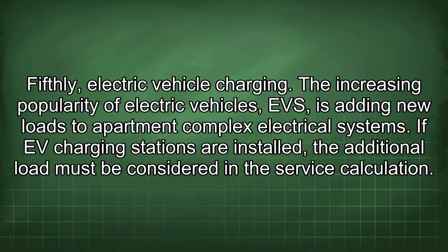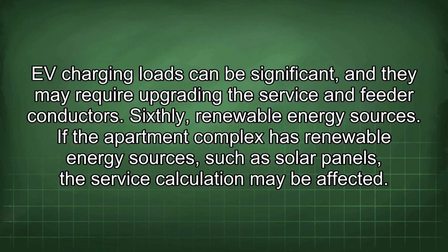The increasing popularity of electric vehicles, EVs, is adding new loads to apartment complex electrical systems. If EV charging stations are installed, the additional load must be considered in the service calculation. EV charging loads can be significant, and they may require upgrading the service and feeder conductors.